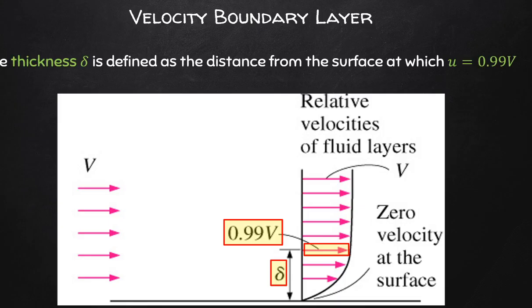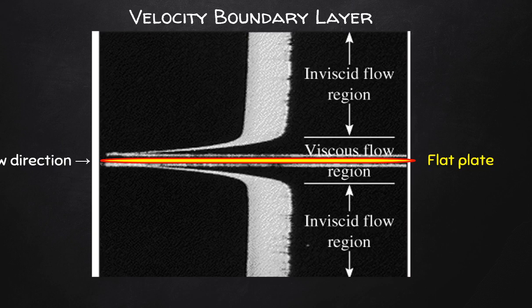This boundary layer, the velocity boundary layer, can be very, very small, and it is defined from where the fluid is stationary on the flat plate until the velocity within the boundary almost reaches the bulk velocity, which is shown here as a capital V as it approaches the flat plate. We have come across this concept. So we have some knowledge about the no-slip condition before. We dealt with this in transfer processes last semester.